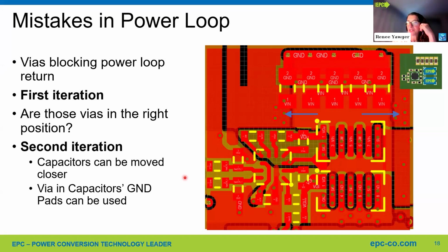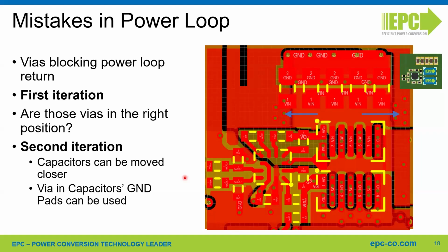Do you have any recommendations for VDS DSAT sensing? VDS DSAT sensing is very difficult. It happens at very large currents. It can be used, but due to the fact that most of our devices have very low RDS(on), the tripping point for the VDS sensing can be very low, in the order of 100 millivolt or 200 millivolt.